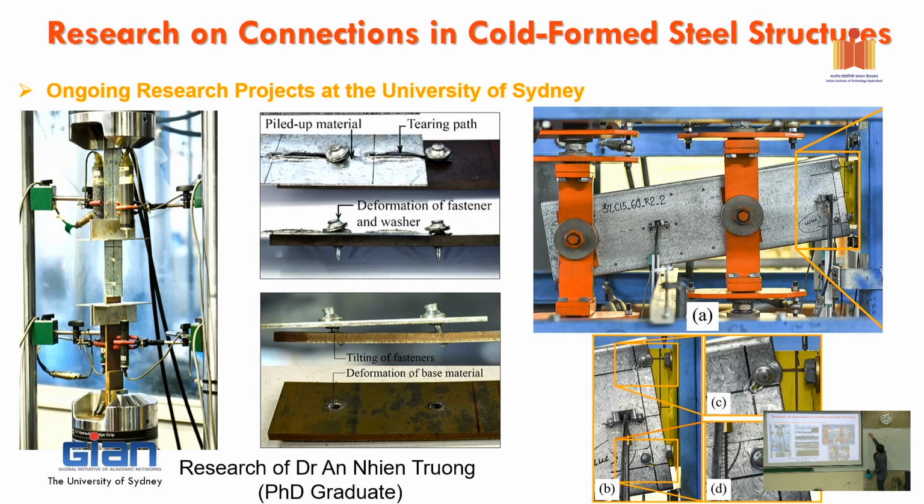So what happens is we have two actuators to bring it down in here. That actuator creates the shear load, as you can imagine in practice. And this actuator pushing down, we can control the rotation. Because the beam in practice, and the connection, is not just subjected to shear, it's subjected to bending, and when it bends, it rotates. So that combined rotation and shear might reduce the connection capacity in the combined action. We don't know how it works.